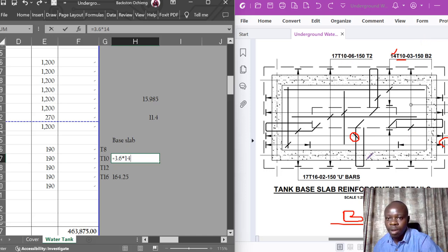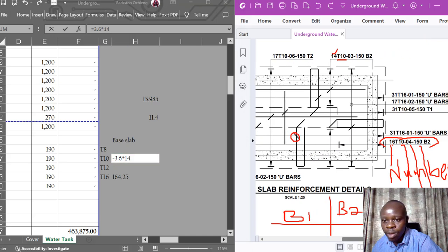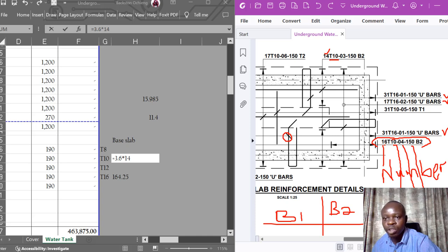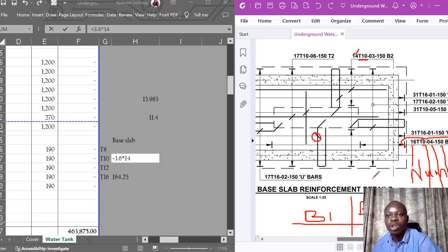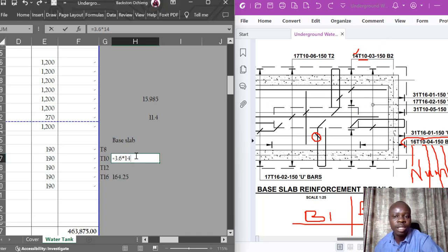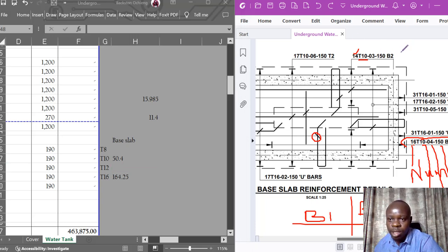You go along within the same plan. Just check if there is another reinforcement bar that is also marked as bar mark 3, because all bars that are marked the same, having the same mark, are normally given that mark because they are of the same length. So 3 is done, just tick. Then I move to 4.